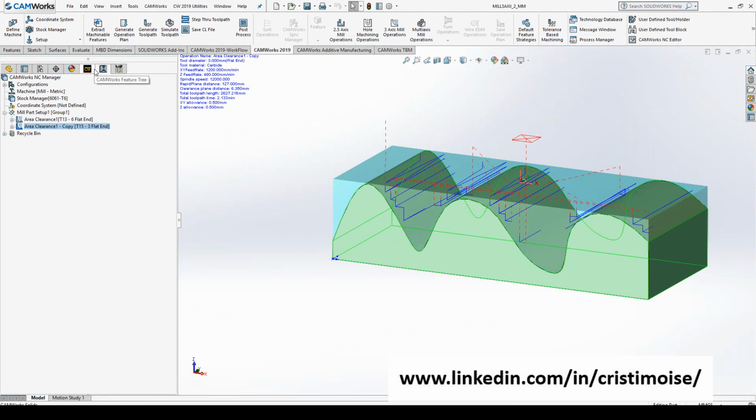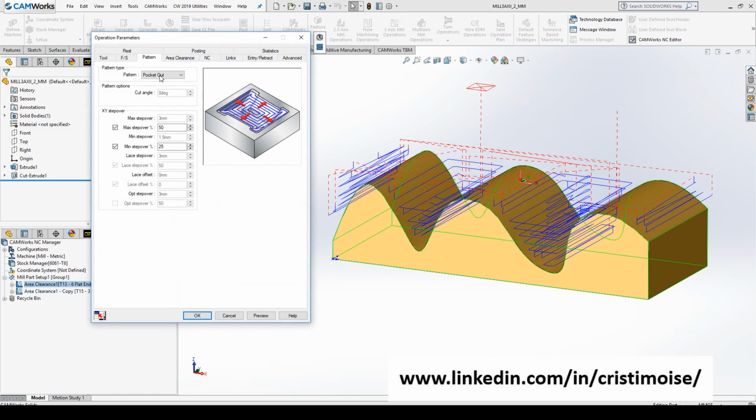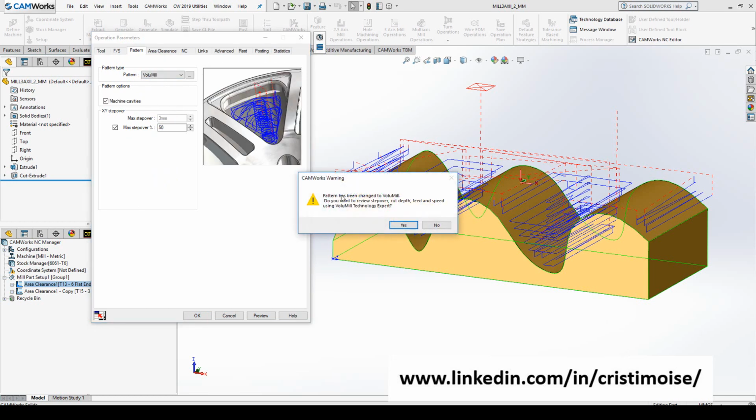Another good enhancement is for the 3-axis volume mill toolpath. You have the ability to use a new function which is called holder avoidance. Right now, you will have a new option which is called holder avoidance. You will just need to enable it. Just click enable. Also for volume mill, let's try for this, and I will show you where the new function is. Volume mill.